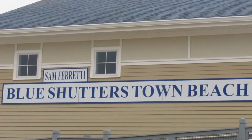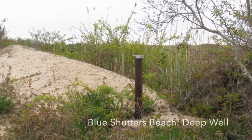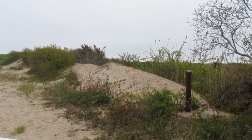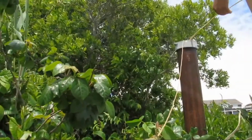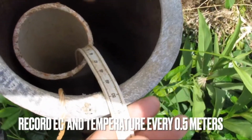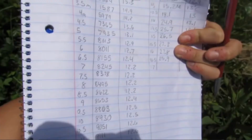As mentioned, our surveys measure bulk resistivity. If we have a well in a survey location, we can get what is called ground control, which validates our ERT data with point data of the water level and electrical conductivity from a well. Using an EC meter, we monitor a well every half meter, collecting electrical conductivity and temperature. This is typically done every 2 weeks and gives us a baseline of the water table to compare to.